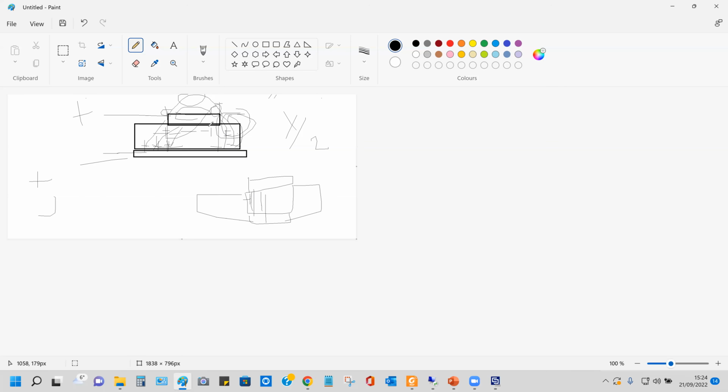Until this point, the fields will be confined within this portion. The moment you extend beyond it, it will see some kind of fringing field. This field is called the fringing field. In a patch antenna, these fields are the only ones contributing to the radiation. This only causes the radiation, basically.